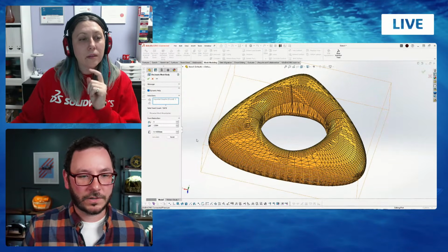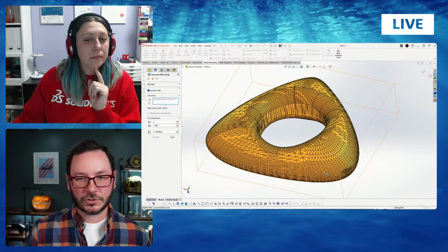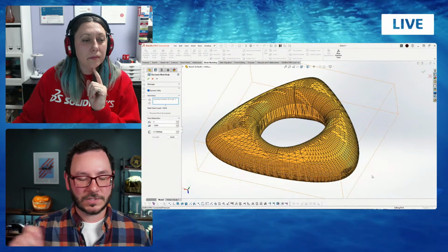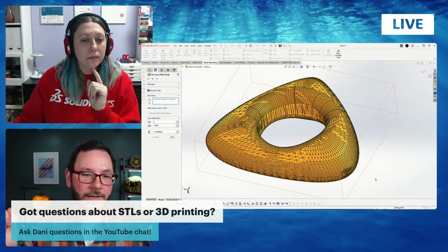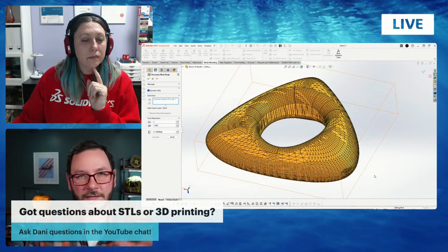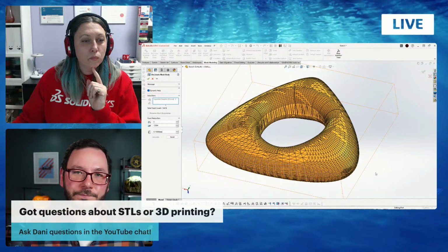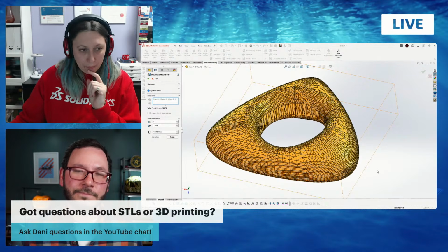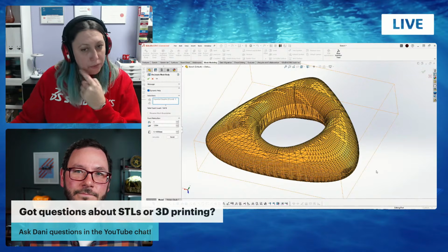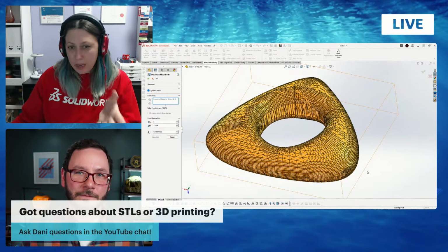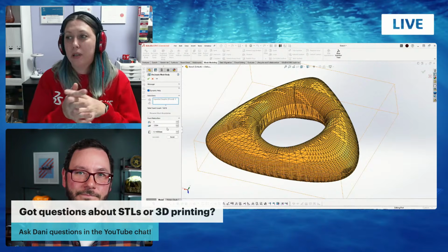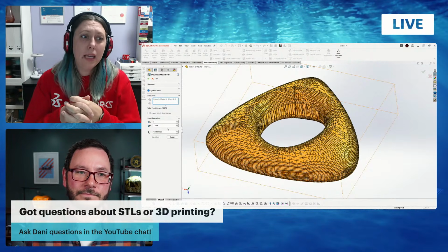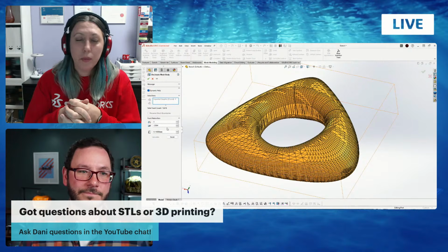Now, do you have a target for what you're trying to hit when you're doing this, or is it just kind of by experience that you're trying to figure out? Like, are you just looking at the mesh itself and saying, okay, I can reduce it by this much, and I know that that's going to still get me what I want, or is there some number that you're usually looking to hit? Depends. It depends what kind of geometry I have, because this stone is kind of simple. I can reduce it a few times by 5, and it still will be fine. But if I have, for example, a dragon, then even 5% can be too much.